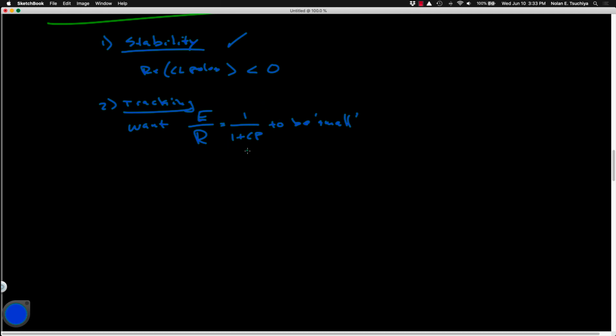So in other words, regardless of whatever R is, the error is going to be pretty small. Okay, so looking at this ratio as a simple fraction, if we want to minimize this ratio, what it means is that we want C, right? C is the only thing we can change in this equation. We want C to be large. If we're talking in pure scalar constants, like just pure numbers, if C is a large number, then this ratio is a small number, and that's what we want. Since we're talking about transfer functions, we want C to basically be high authority. So a large value of C, quote unquote, means that it's a higher authority controller. And higher authority just means that for any given input, the output is pretty large, right? So this is what I was talking about earlier. It's a very sensitive controller in that even for small errors, it produces a large control effort. Okay, so for tracking, generally speaking, we want a high authority controller.